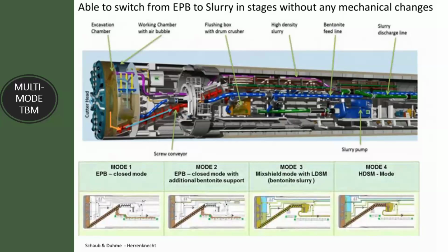Now, the designer fixes the appropriate or minimum number of segments the TBM has to build so it can move from the initial drive to the main drive. It can be 80 segments, it can be 100 segments. So if 100 segments have been installed, we release the reaction frame, and the TBM starts working on the main drive. Then the TBM is moving, it starts building the ring, and it takes the thrust from the rings. So this is basically the movement of the TBM.